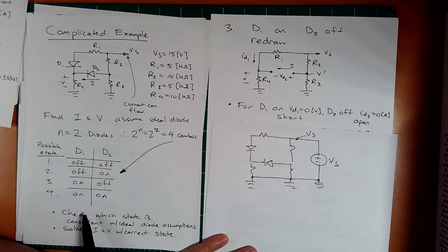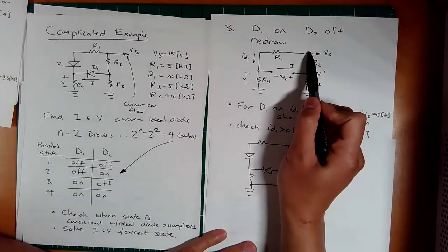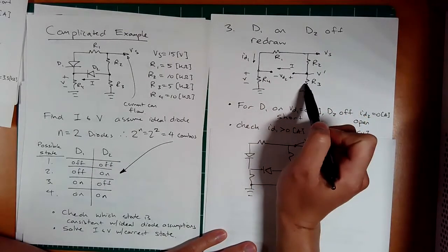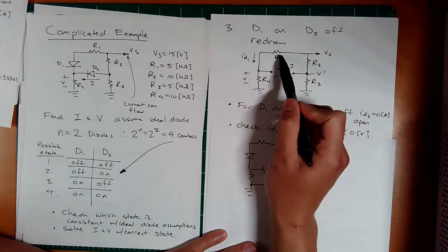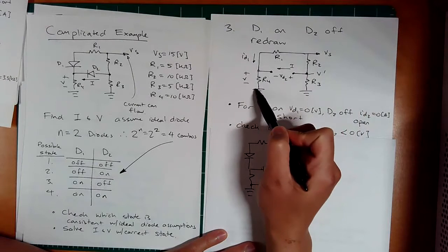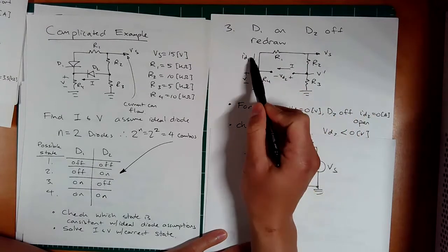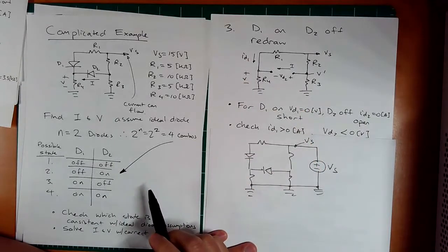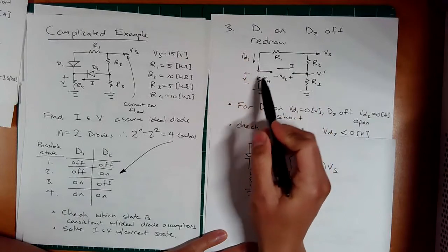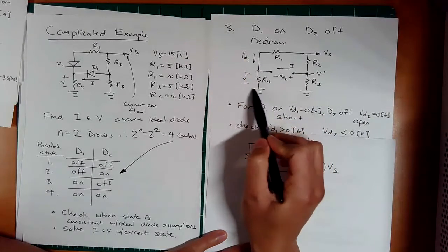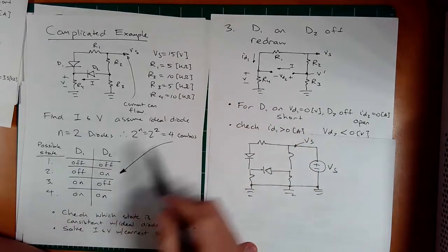All right. Okay, how can we confirm these things are true? We have 15 volts here. We know all these resistances. I can already see this ID1 is probably going to be positive. Look at this. You have R1, R4, and a voltage across it. We can do a nodal Ohm's law on this series R1, R4, and I can already tell this is going to work. That's going to be positive. Okay. If I get this current, then I could actually, by Ohm's law, get this voltage. Is that right? ID1 times R4 is going to be this V. Good. So I can get that voltage.